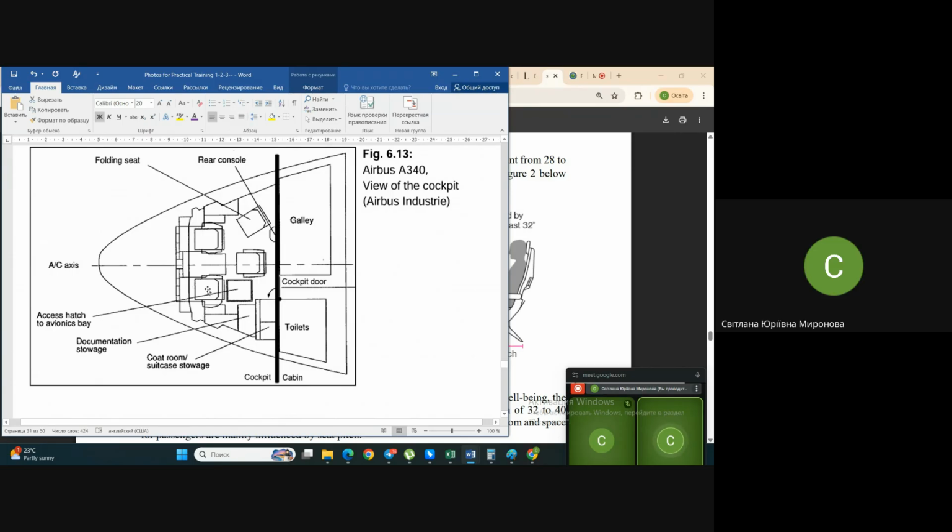So you see, pilot, co-pilot, some place behind them is also necessary. And the distance between pilot and co-pilot should be at least something like 40 centimeters, in order for them to squeeze into their seats, forgive me. And don't forget that this size from one seat to another should be inside the fuselage, so don't make this place too narrow in your picture.